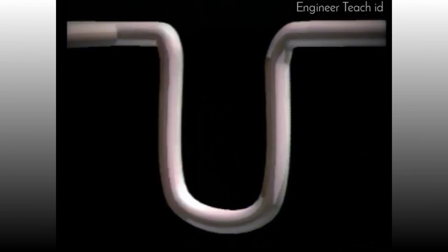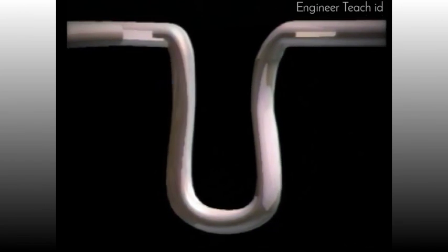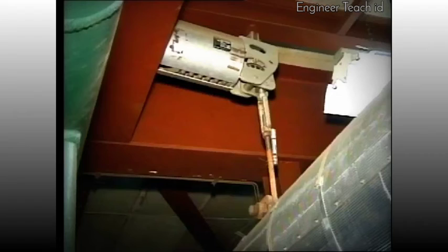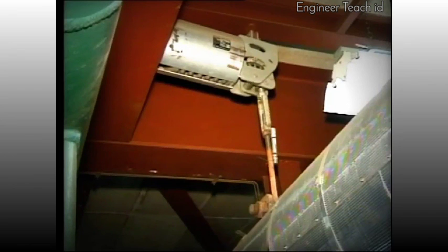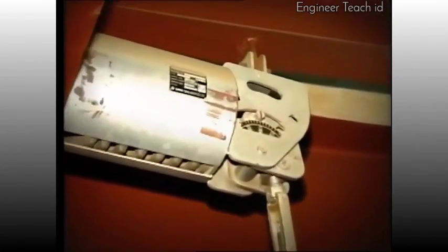The run of pipework is designed with deliberate bends and turns to accommodate the expansion between 2 fixed points, that is the boiler outlet and turbine inlet. The pipe hangers and supports are designed to be flexible and allow movement of the pipe under expansion forces. The operator should make himself aware of the normal position of critical pipe hangers. Often an indicating pointer is fitted to allow this. If a hanger does become jammed and prevents the free movement of pipe, physical damage may occur to the pipe itself or to other supports.